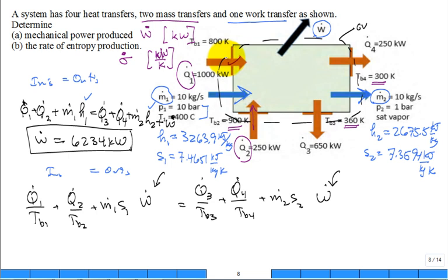And you go back and you think to yourself, how does that make sense? Work is an organized energy transfer. Entropy is a measure of disorder. Heat is, on a molecular level, more jiggling, higher energy, higher temperature, hence more disorder, higher entropy. But a heat transfer is a disorganized energy transfer. So W dot doesn't come into play in the entropy balance equation.